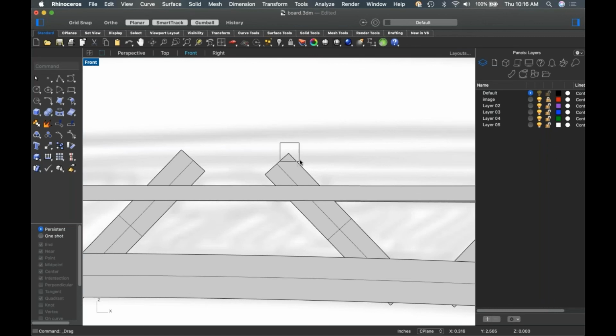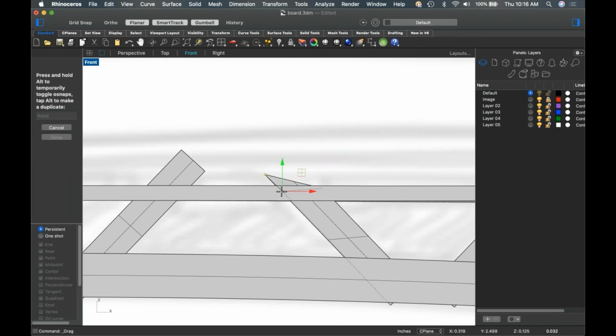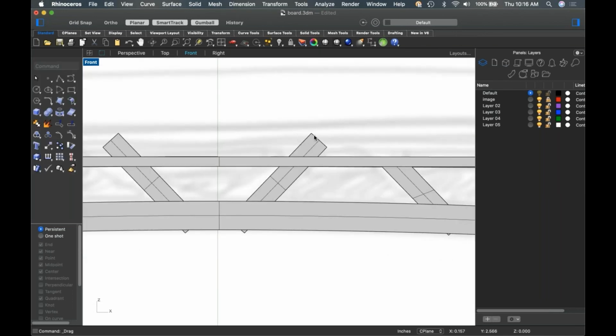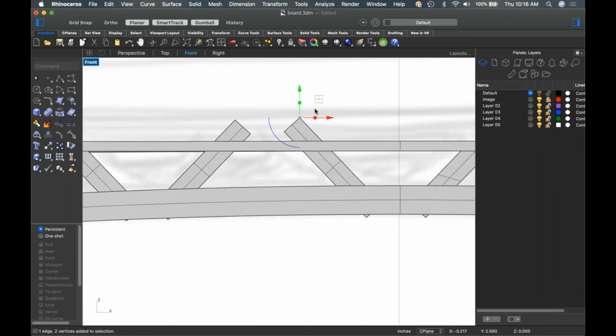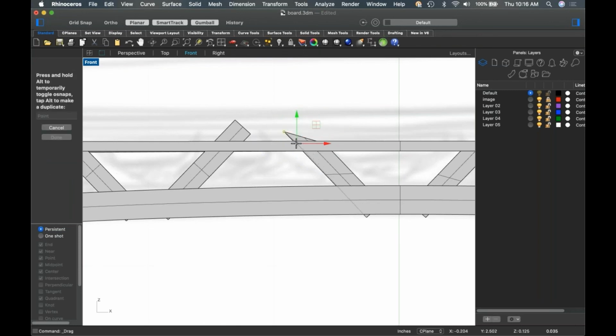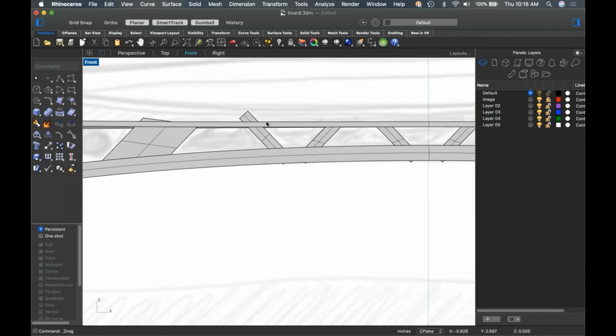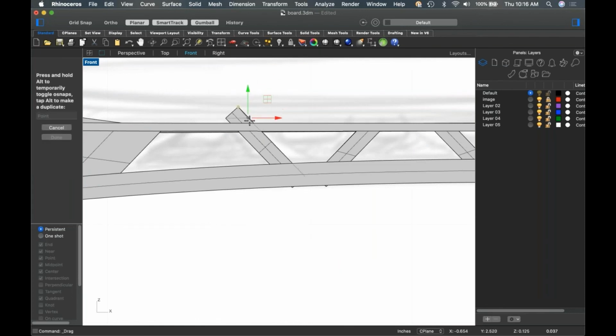The nice thing about degree 1 objects is you can play with the corners like this, these extrusions, and mess with them, and it doesn't make a mess. If these were degree 3 objects, then you start getting a lot of distortion and a lot of isoparametric screw ups, so to speak, and it's hard to sort through them. But this is called sub-object selection and sub-object editing, and it's a super useful thing, especially when you're working with really basic objects. And this is just going to save me a bunch of trimming and stuff.